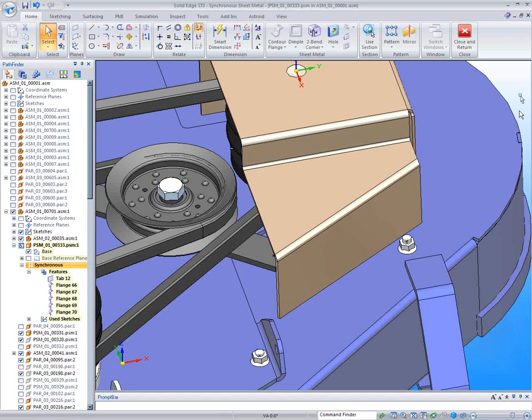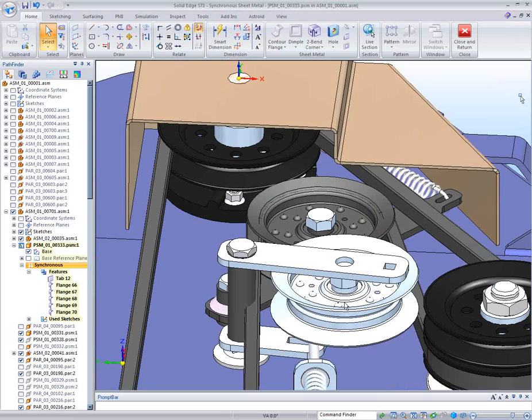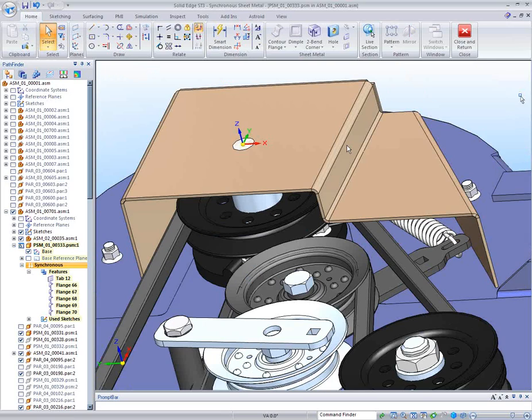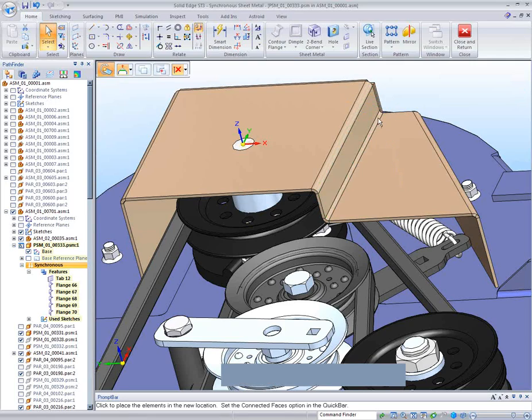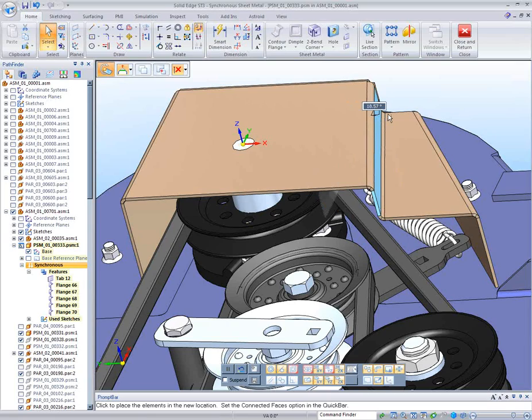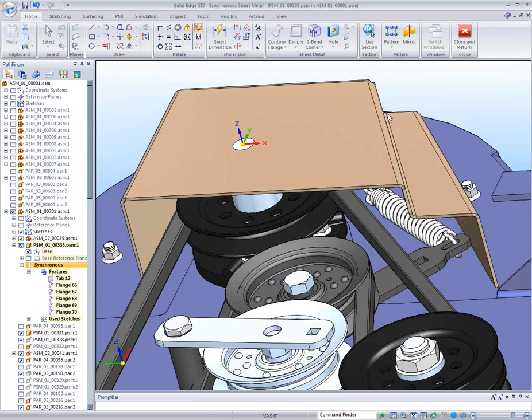Now, I'm going to lay the foundation for this in the future, and I'm going to take this face and do the same thing as well. And I'm just going to bring this face over just a little more. Okay, so I might bring that over about 25 degrees there as I have that, and we'll hit tab. I believe I said 35 millimeters on the last one, but I meant to say 35 degrees.